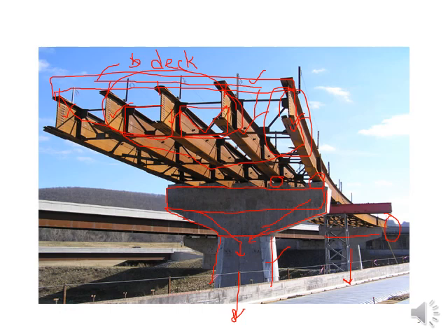So the load analysis for the interior stringers we have to do separately, and the load analysis for the exterior stringers we have to do separately. But we are providing the same cross section throughout, and we are going to be designing it as a plate girder. All of these are the girders. So the girder bridge means you are going to be designing it as a plate girder that you have done already in your steel structure course. So you have to design it by yourself at the end of our example problem.